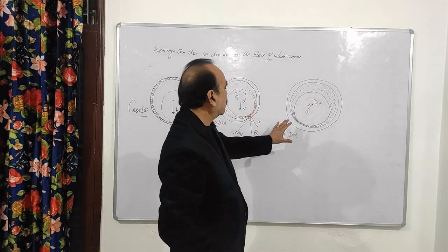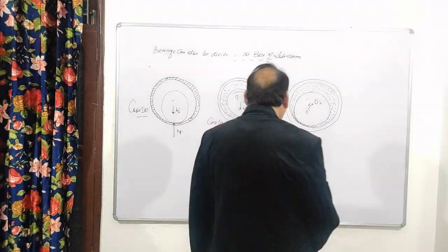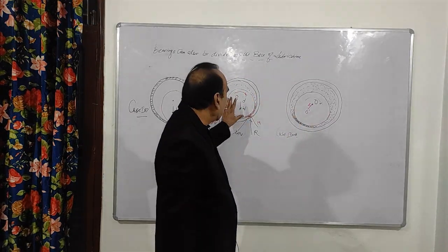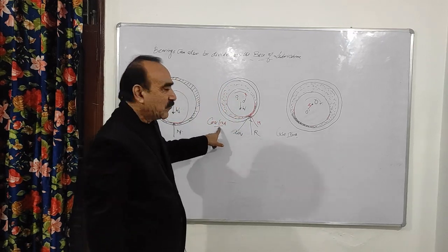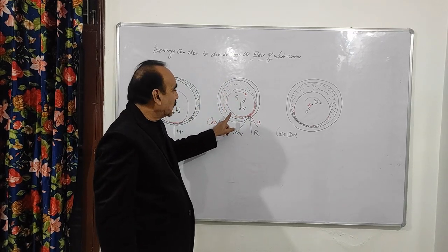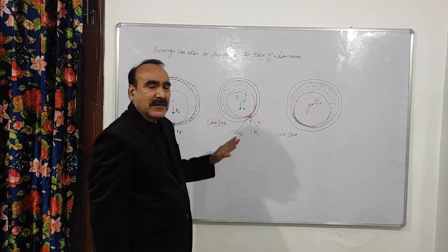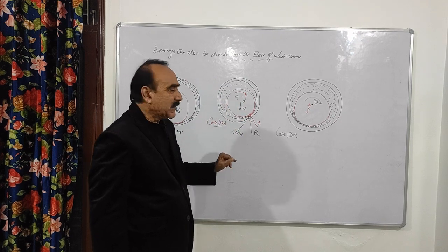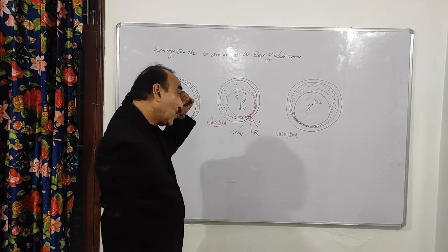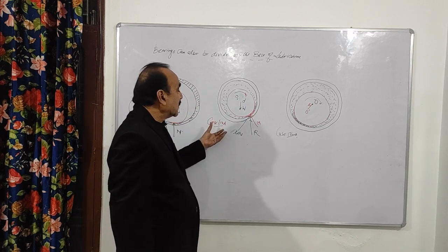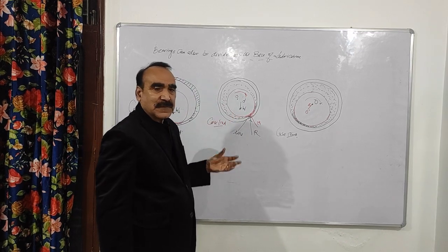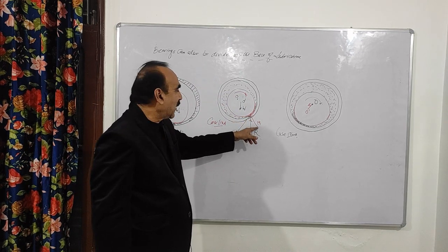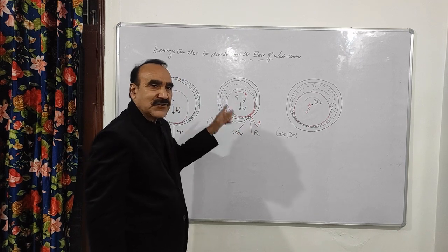So here you will see, this is the final case, the case number third. This is the final case of this. So in case number second, I have explained that the shaft has just started rotating. It has not attained its full operating speed, right? So at this time, the load of the shaft is supported by the resultant force, which is acting in the upward direction, the resultant of the normal force and the frictional force.